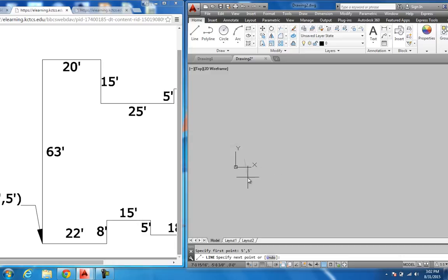Now, in the direct line method, it's really easy. Down here, we've already looked at the status bar, but we quickly know that this one right here is what we call object snap. And that's what allows us to snap to end points, mid points, center points, and things of that sort. Makes it really neat and really handy to be able to click those points. We also got this other tool over here we call ortho. Now, ortho means 90 degrees, and what that does is you can see you can either draw horizontally or vertically in the X and Y direction.